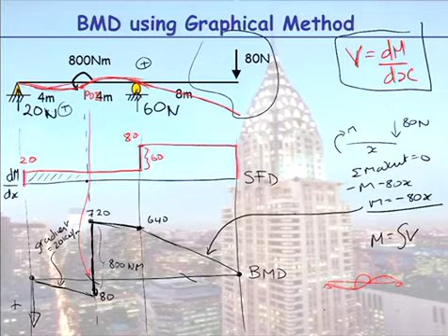So thus, in terms of my bending moment diagram, my bending moment diagram would be down here, and then it has to come up, so it must be a step up. You can remember it however you wish, just draw it such that anti-clockwise is a step up.